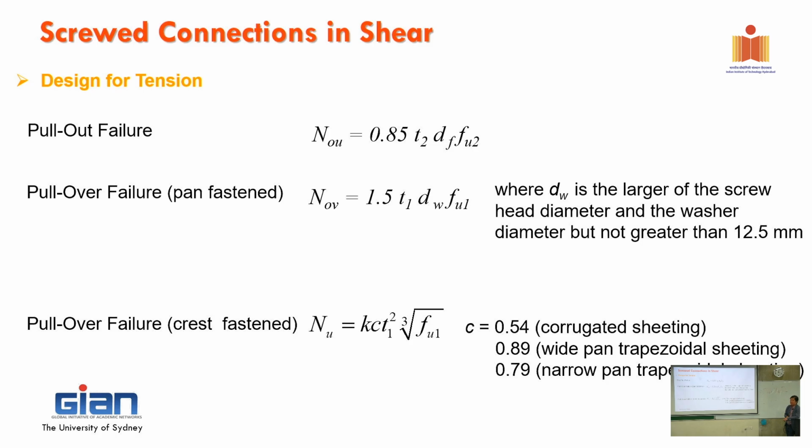So we did a lot of tests recently because you remember the dimple holes that I showed you before? Because they have the pre-drilled hole, then we have to use the self drilling. So the shape is a little bit different. They don't have the tip to cut. But the thread is a little bit deeper. I don't know why, but that is how it works in practice. But for those type of screws that we use for testing in here, the diameters of inner and outer, including the thread, are not much different. So that's why we can use that equation.